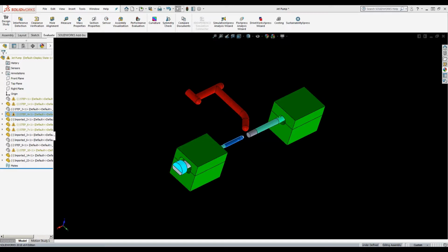Does building prototype molds with pick-out cores and having the anything-it-takes mentality do more harm in the industry than working through production issues up front? Sometimes designs get all locked in based on prototype methods and are impossible to make in production. Really good question. It can happen. We try to do our best up front, due diligence with our customers, to express that even though it can be done in a manual environment, it may not work in the production environment.